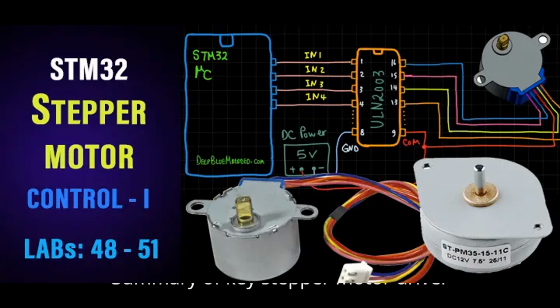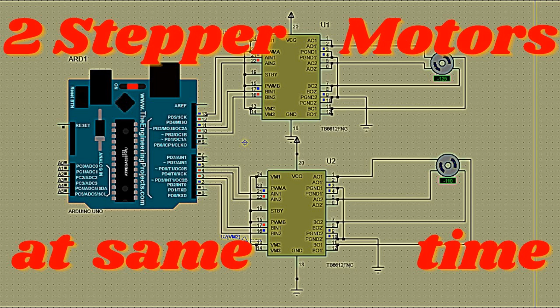Summary of key stepper motor driver features. Current control: stepper drivers manage the current through the motor windings, which determines torque and stability. Step control: the motor's movement is controlled by the number of steps or pulses sent to the driver, with microstepping offering fine resolution. Modes of operation: full step, half step, and microstepping offer different performance trade-offs in terms of smoothness, torque, and speed. Heat management: many drivers include features like chopper circuits or current limiting to prevent overheating and improve motor performance. Position feedback: closed-loop systems incorporate feedback to improve motor efficiency and reliability.